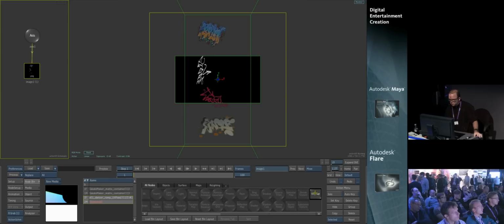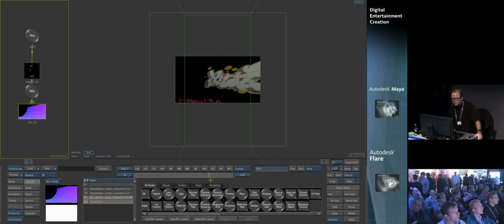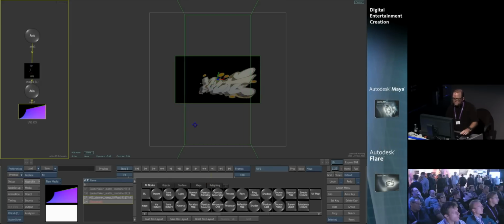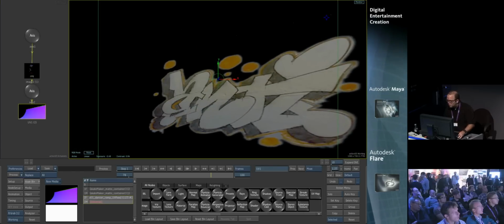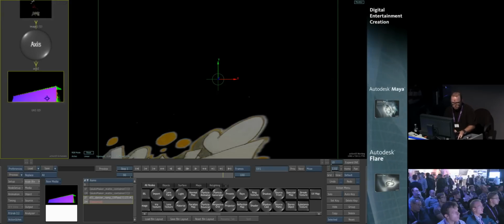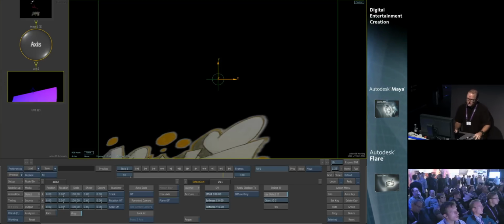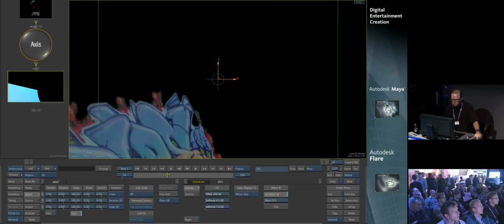And you'll notice as soon as I throw it in here, it's going to instantaneously distort that UV in the perspective that is designed for this. And you can see how that works as a ramp. If you want to get into some of the granular detail, you have artifacts such as the edges of this plate appearing. So you see how you've got extra UV data in here that we don't need. I would take advantage of my object IDs. So in the blue channel of a UV pass, you have the ability to pick just ID 3, and you can see that isolates out just the ramp. And now I've got a nice clean ramp thrown in there.